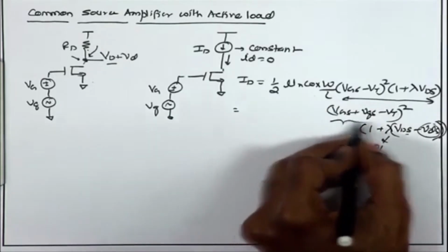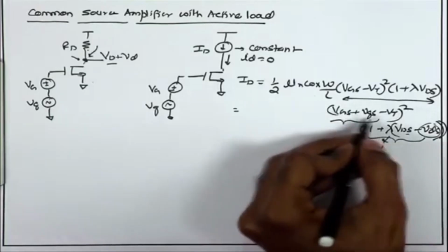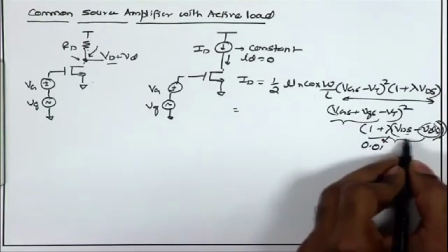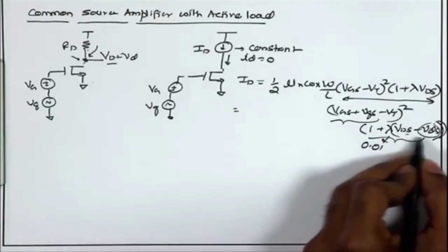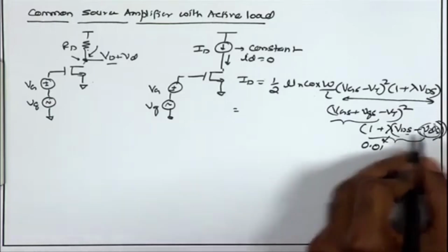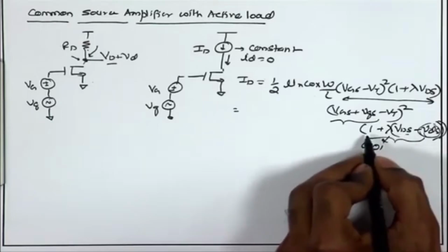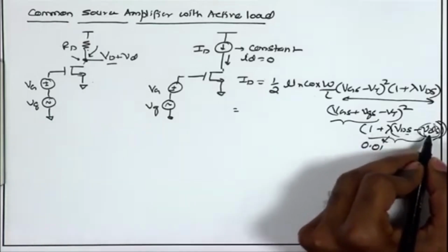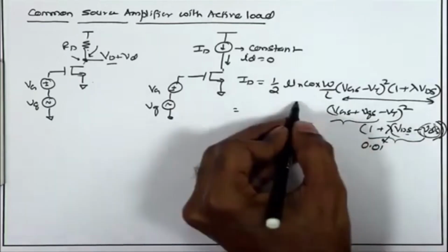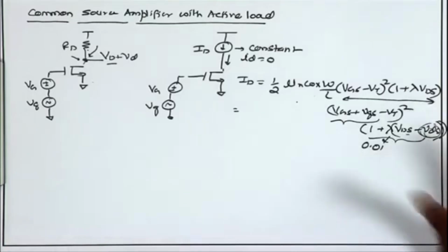The increase in the first term has to be balanced by the reduction in the second term, and in order to counter this increase arising from this quadratic term, I must have a pretty large reduction in VDS, because this is getting multiplied by lambda and then resulting in the overall term. So, that mandates a large reduction in VDS to compensate for the first term, so that the product remains constant. That is the basic mechanism for obtaining gain in this circuit.